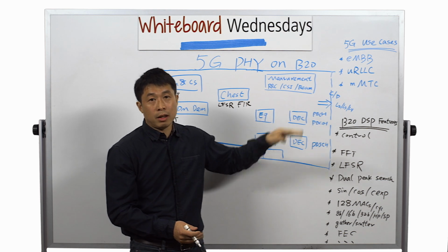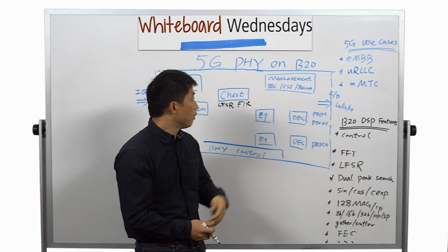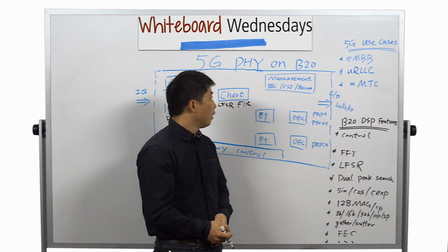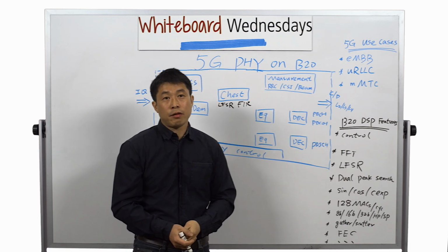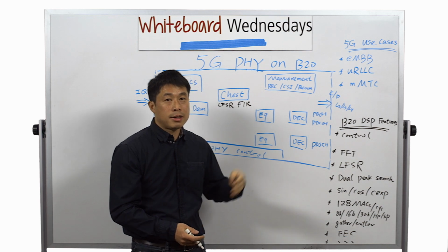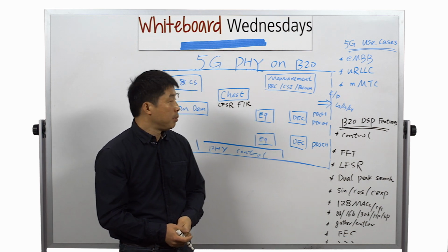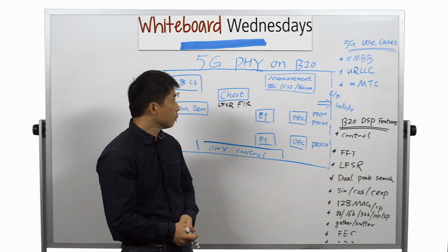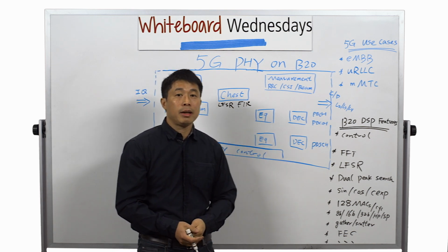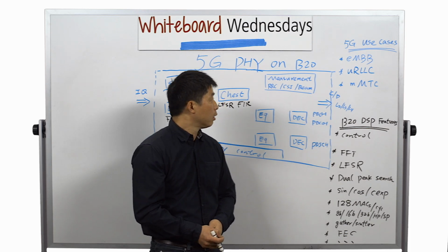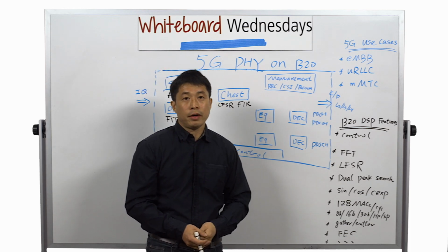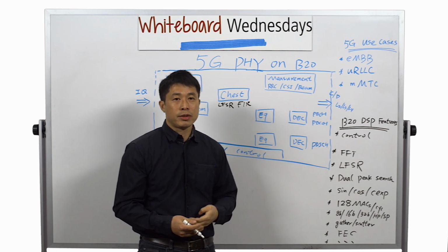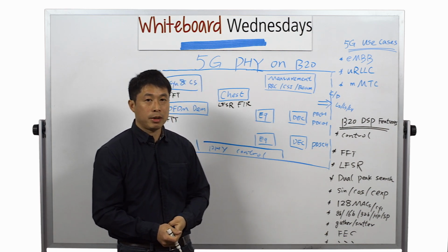In 5G modem, there's a lot of measurements to do. RRC measurement, RSRP, RSRQ, and CSI, channel state information measurement. It selects the RI, PMI, and CQI and sends it back to the transmitter side. Beamforming is a key enabling technology for 5G. In the measurement module, we need to do the beamforming measurements to select the best beam for the transmitter and the receiver.